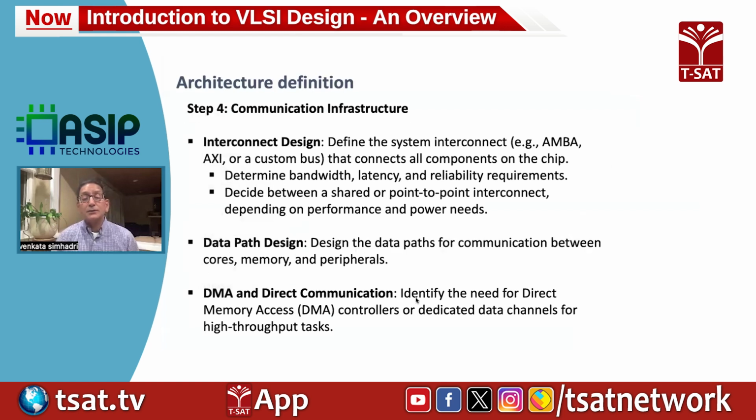Then all these blocks need to talk to each other on the SoC. There's something called system interconnect. There are standards like AMBA, AXI, or you develop your own custom bus. The AMBA bus, as I said, is based on determining the bandwidth you need, the latency and reliability requirements. And then if you have a data path in your design, you need to define and architect that as well.